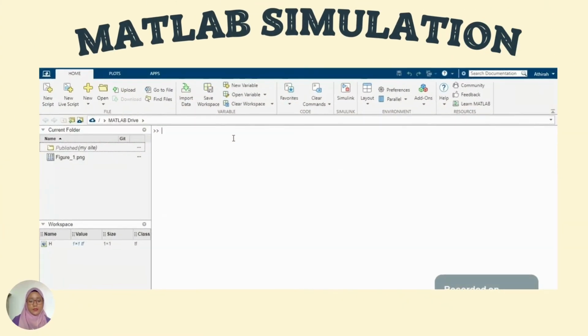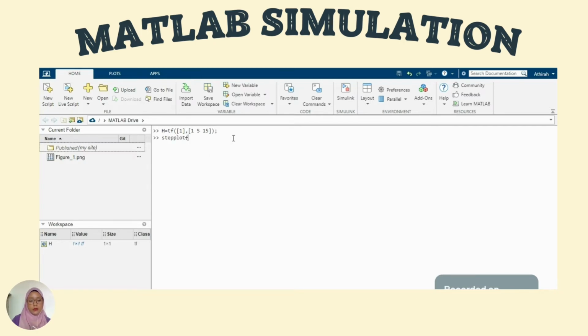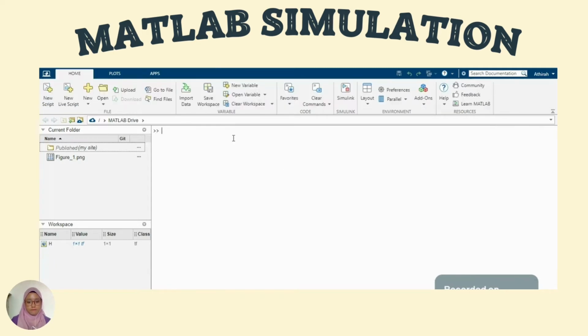First of all, for our MATLAB simulation, we need to insert the input at the command window to get the system response. We use h equals tf, and we insert the values that are 1, 1, 5, and 15, and then we use the command step plot h. After that, we press enter, and the graph will be shown. It takes a while. Okay, the graph is shown.